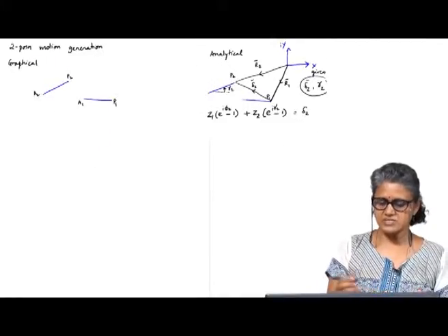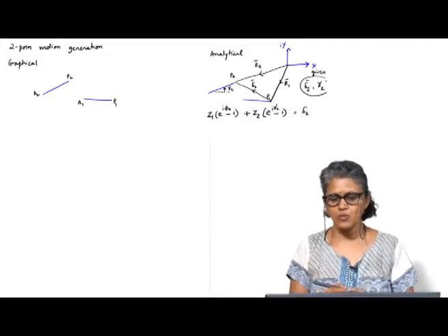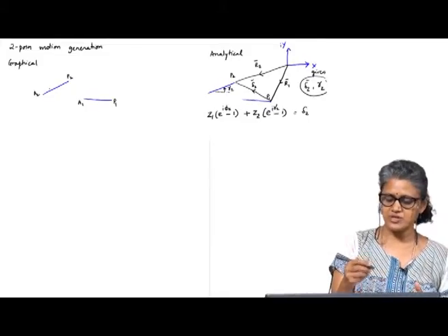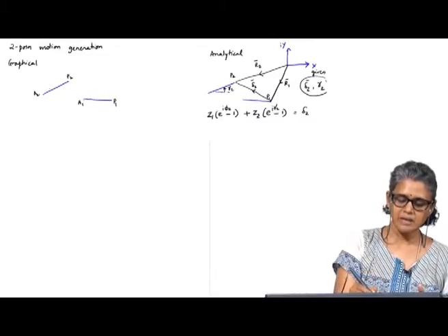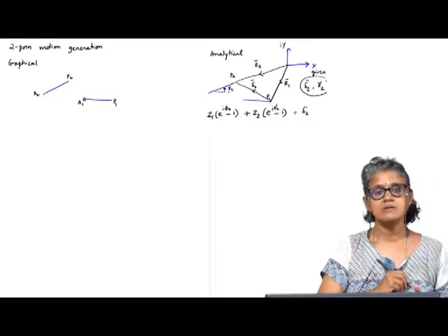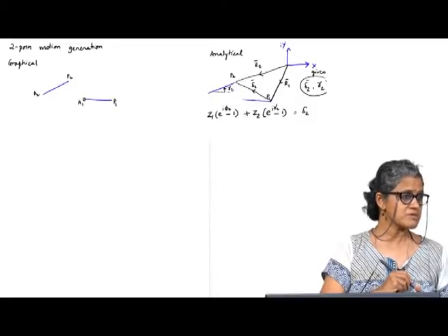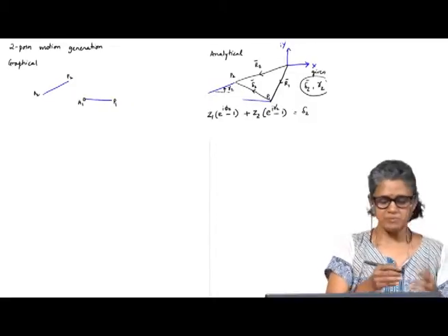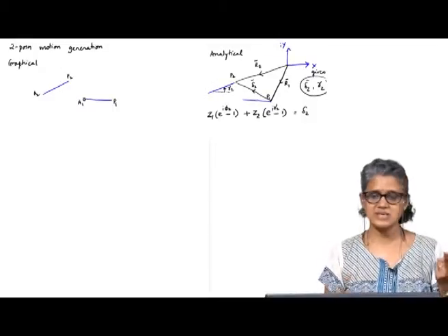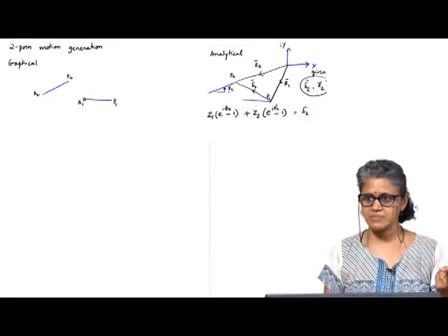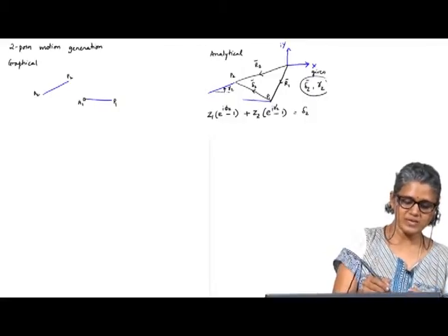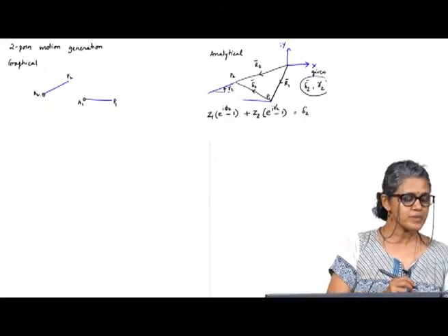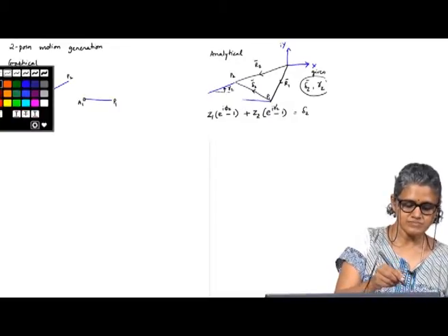So, the difference is, here the way I exercise my free choices is I pick A1 to be my moving pivot. I can pick anything else also. So, I exercise 2 free choices there. Now, A1 I know in the second location has moved to A2.